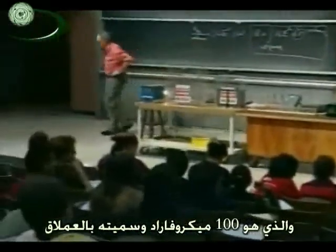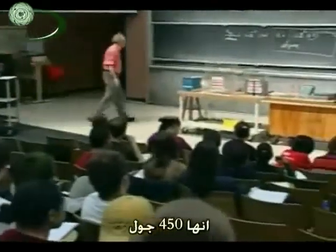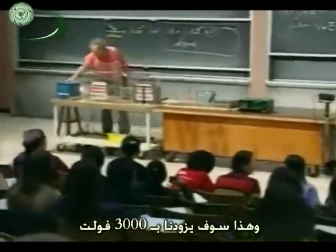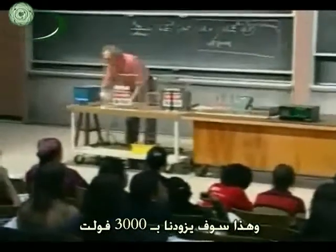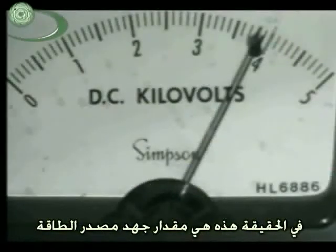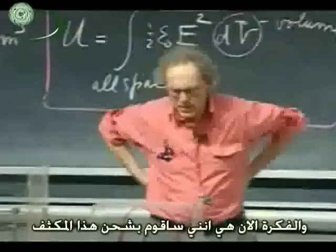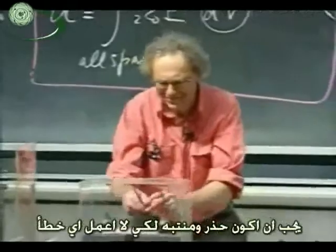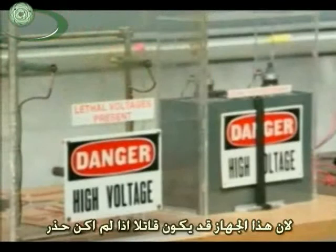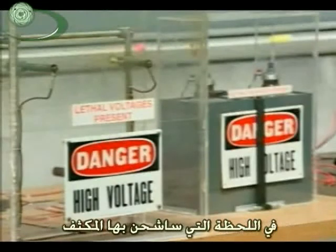So here is then this monster, the 100 microfarad. I call it a monster because the amount of energy that you can pump in there is frightening. It's 450 joules. And my power supply is here. That would deliver comfortably the 3,000 volts. In fact, this is the voltage of the power supply. This is about 3,800 volts. And so now the idea is that I'm going to charge this capacitor. I always have to be very slow and careful that I don't make mistakes, because this is really a device that could be lethal if you are not careful. So I think we're okay.